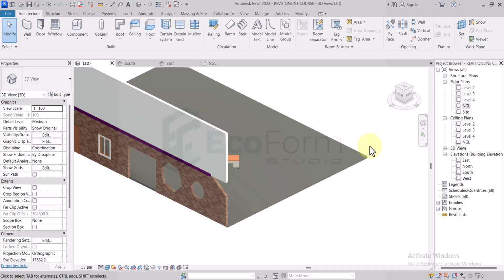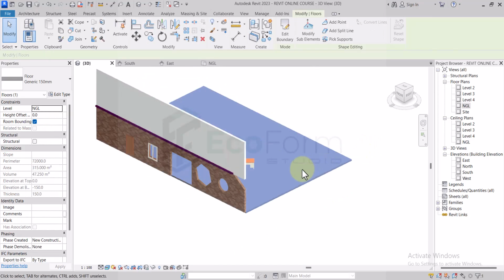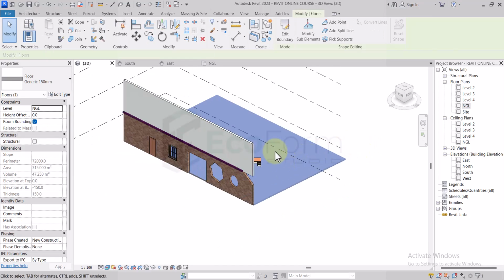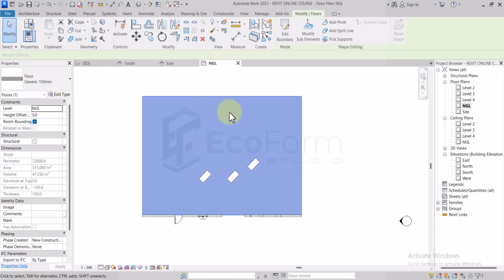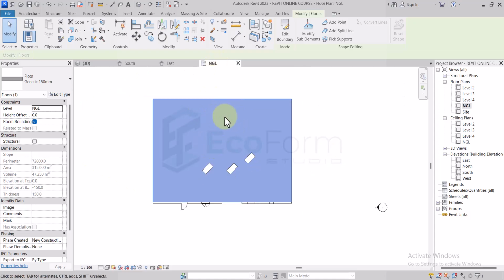Now, moving on, let's create an opening on the floor. It's simply the same process, just that we are not going to be creating that on the elevation view. Since it is a floor, we are going to be editing it on the floor view. So after selecting the floor, go to a proper floor view where the element is being placed.